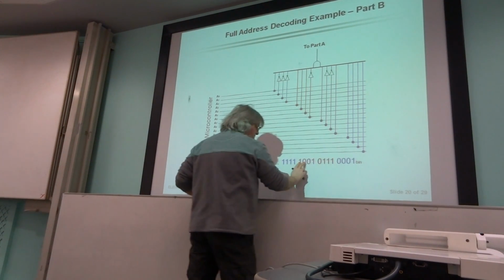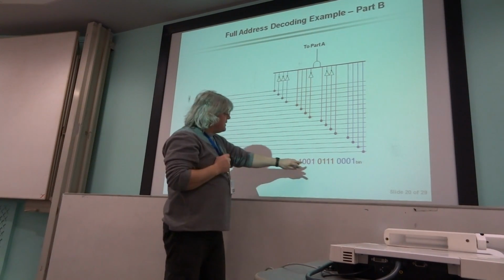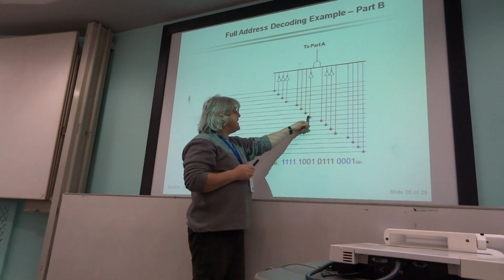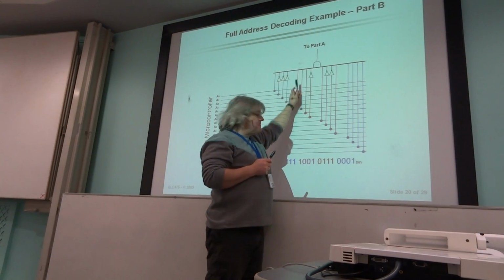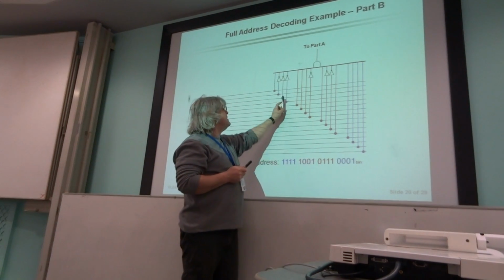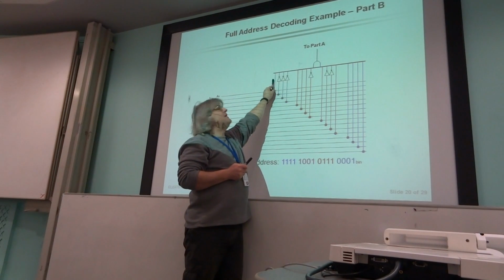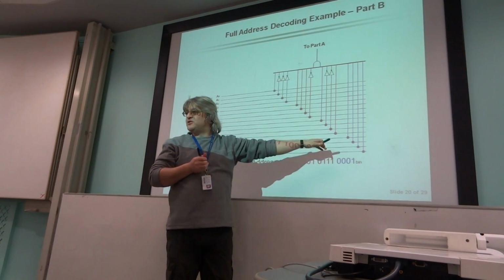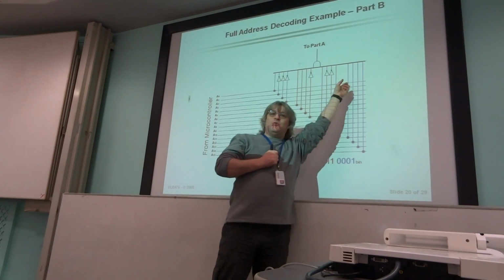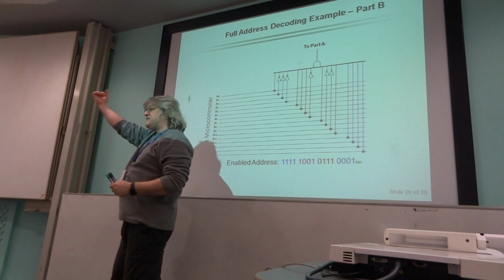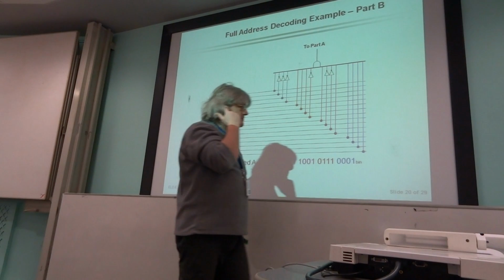The inverters here will take those 2 lows and make them high at this point. So you'll end up with 4 highs here. Then you have low, high, high, high. Well, there's that low, but it's going to be inverted to make it high. So they'll all become high. And with this particular combination here, low, low, low, high, that's going to be inverted to become high, high, high, and that's a high. So they all go high for that combination. So if that combination appears on the address bus, the output of this AND gate will go high, which will be another means of pulling down that NOR gate and making it go low, waking up the device.